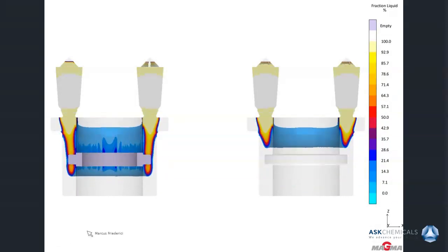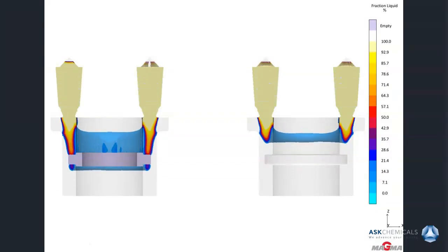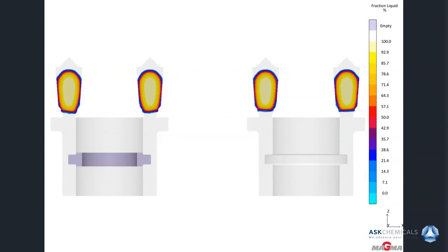But I stop it here. You can see our problem. It's behaving just in the thermal way, like extra material. So we have no material transport through the padding, which, of course, you can imagine is not possible because it's not steel or iron or any type of metal. So therefore, you will also have here a section which is not connected to the rest of the solidification, even if it's looking good in a thermal way.